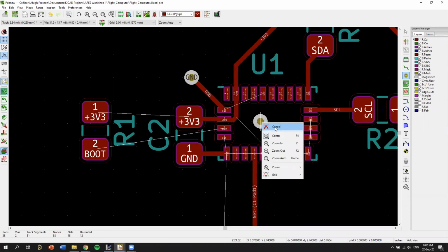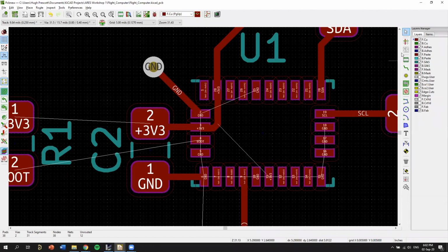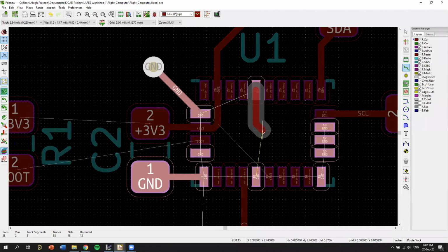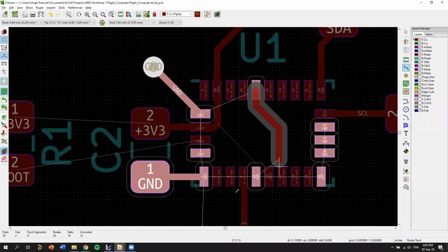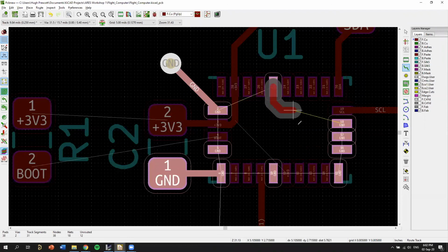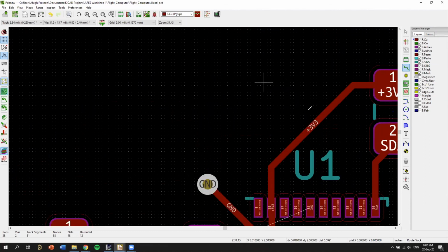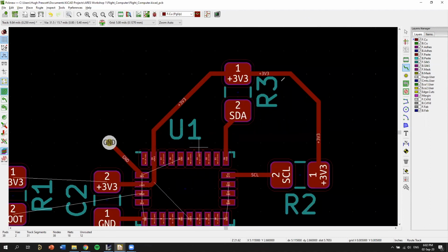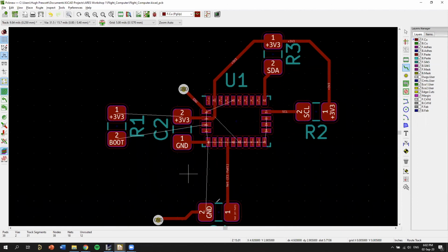And then you see where it can get complicated now is, okay, what if I wanted to connect this pin to this pin here, pin 2. Now I've routed it in a bad way because I can't just draw a direct line. I have to go all the way around here and then all the way around here, or I've got to go, you know, there's like trade-offs to everything. And normally to solve this, we use the back layer of the PCB because that provides like a whole extra dimension so you can run traces under each other. But it gets complicated quickly and it can be very difficult to route some things. It just takes a lot of planning ahead to do it right.